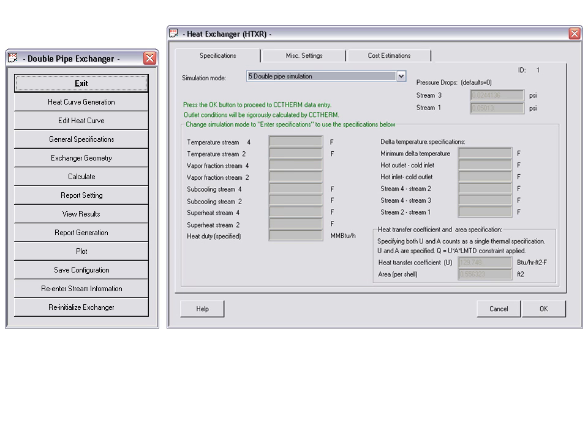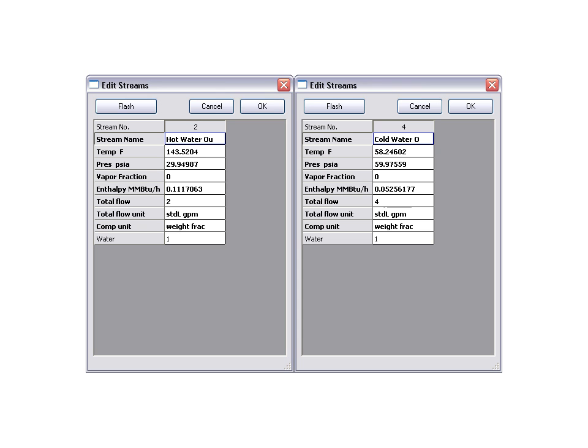Note that all the temperature data for the various streams has been grayed out, and this is where ChemCAD will be using the information it calculated in order to determine what its predicted outlet temperatures are for the heat exchanger. After clicking OK, we run our program and look at our outlet streams again.